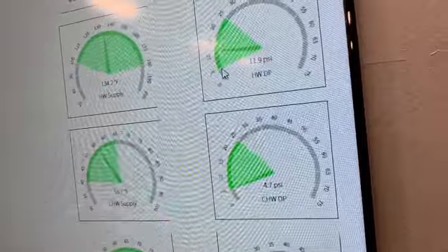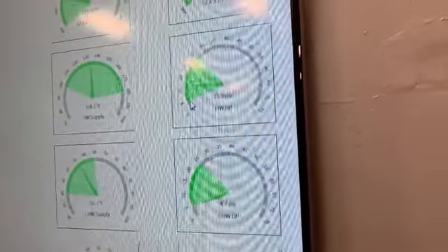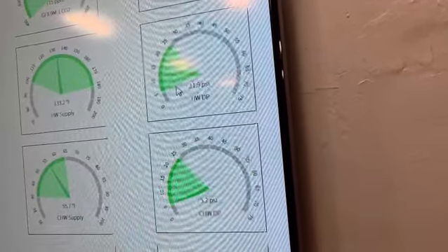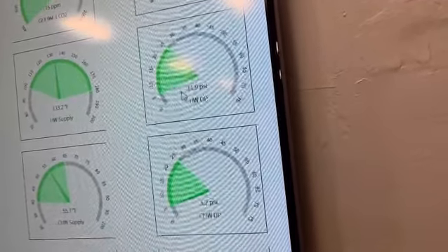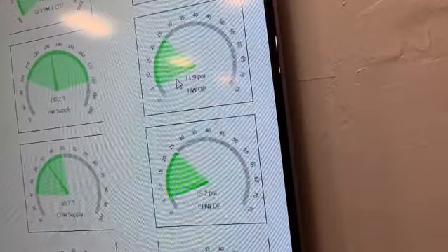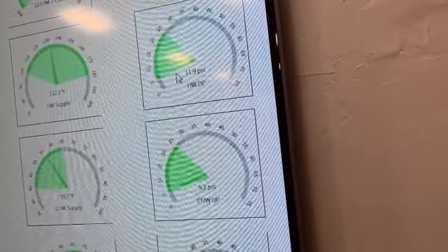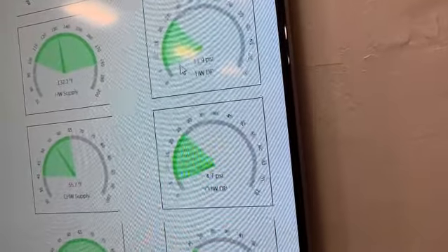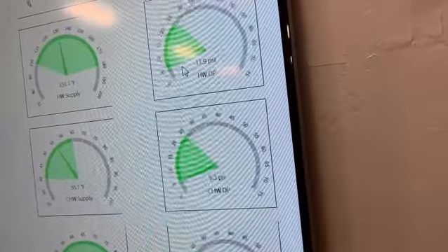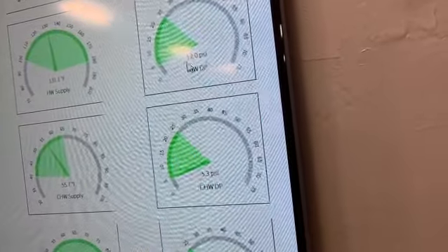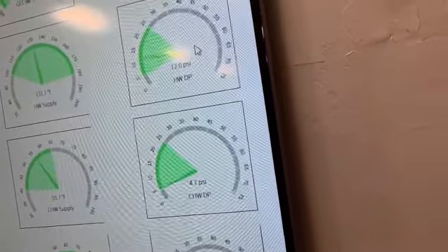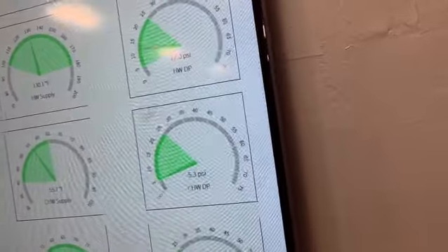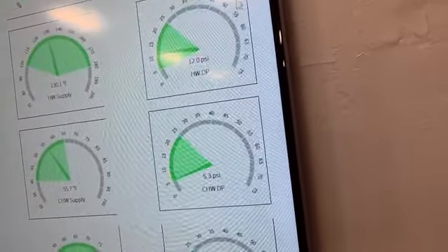So if the pressure drops or increases, it will affect the pump's speed, right? If you need more pressure because someone starts opening up water or losing water for whatever reason, the pump will ramp up and increase the pressure until it reaches the set point. These are installed on the pipes. This one is hot water DP. So these are all boiler stuff, right? This is boiler, yes.